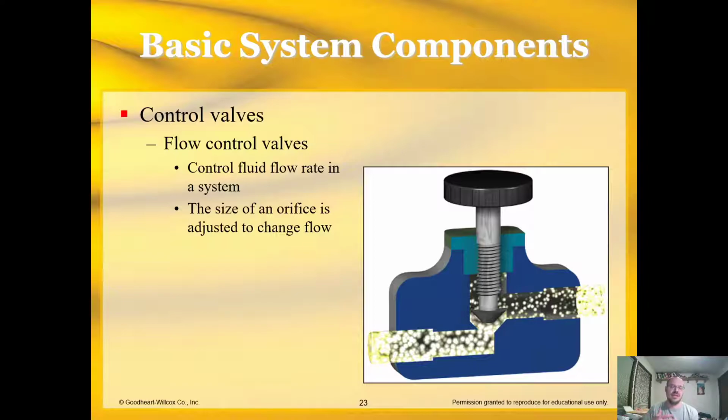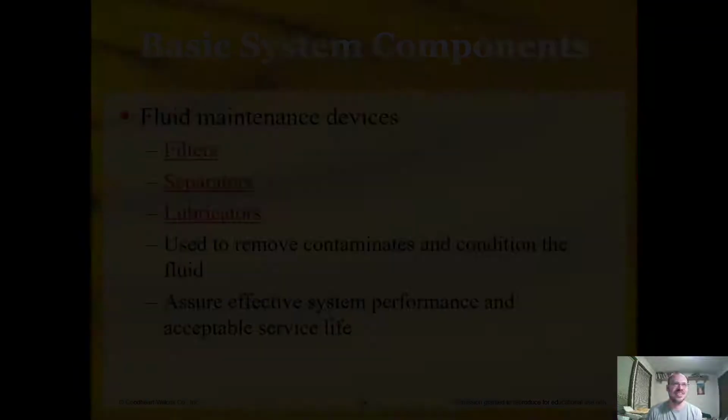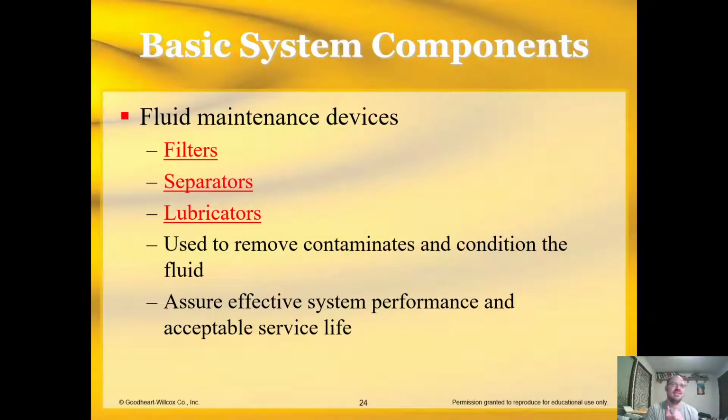But that's, again, that would be your thumb over a garden hose, right on the outlet, yeah, it's sped up, but that would be more of a nozzle case, I guess. In this case, it's more of decreasing the speed the more you have your thumb over it, because you're actually decreasing the flow rate, right? Sorry, so maybe the thumb over the garden hose isn't the best thing to think of there.